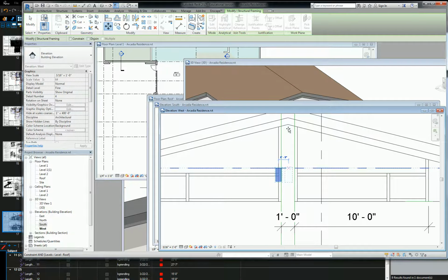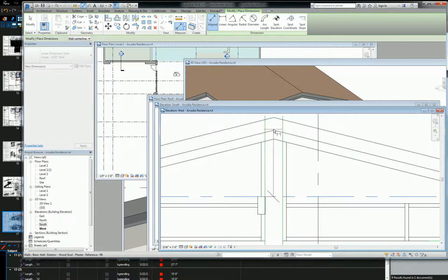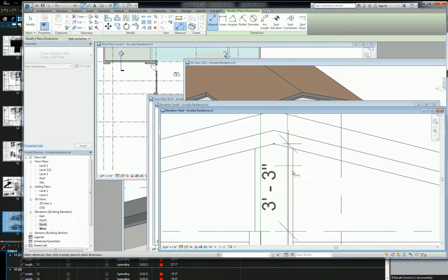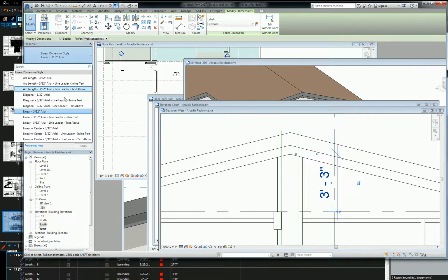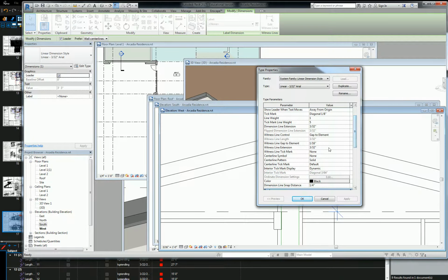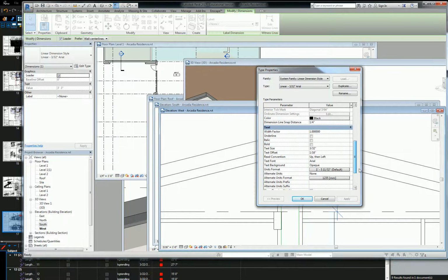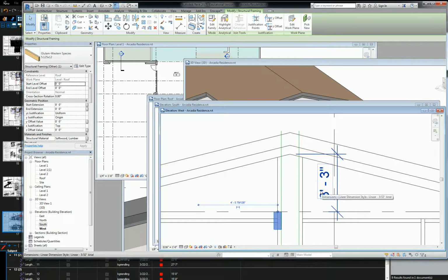So anyway, what we need to do is measure the distance from this level to, I believe it's this point. Let me pick something, I want to just double check something to make sure this dimension doesn't round it. It doesn't. Okay, so that's exactly 3'3". All right. So since we're measuring to that point, what we've got to do is move our beam 3 feet 3 inches up.